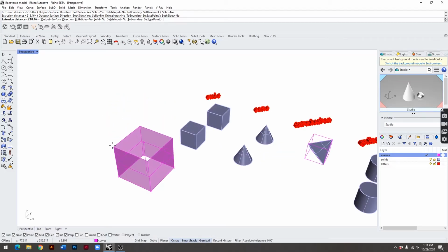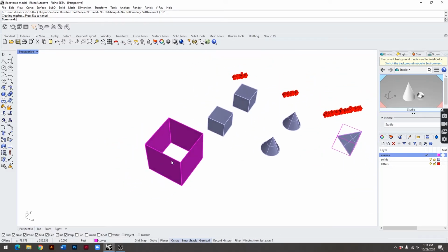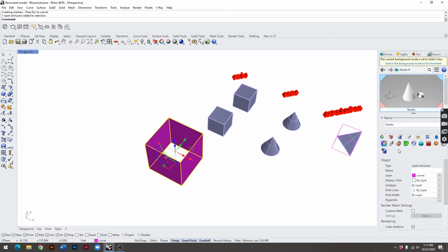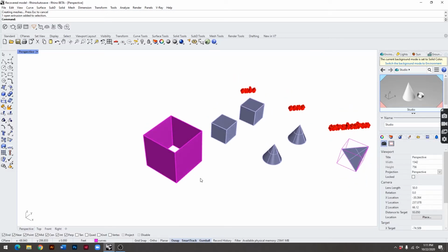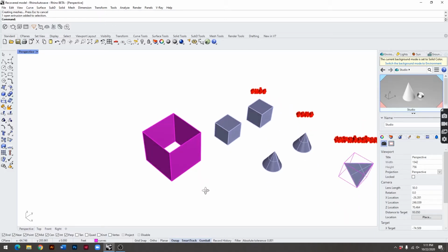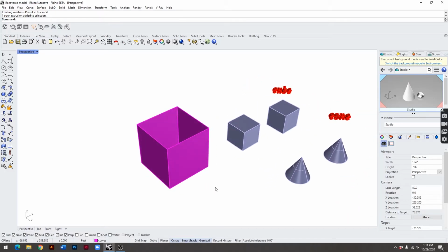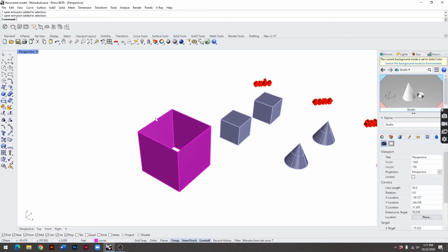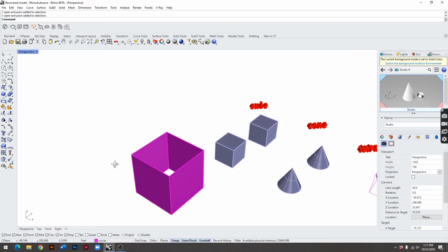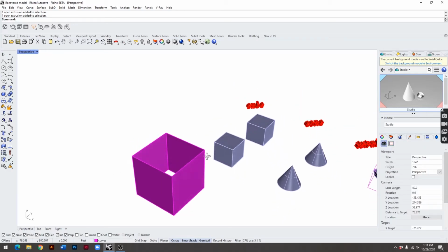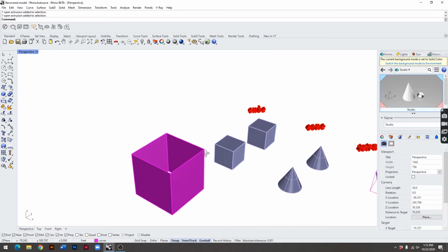If we don't want it to be solid, we'll just do that, and you'll see that we have an open extrusion. In Rhino, closed extrusions or closed solid polysurfaces are like the gold standard. That's what we always want to have. There are all sorts of benefits to having closed solid polysurfaces as you progress through architecture, and it also just forces you to make clean, good Rhino decisions.